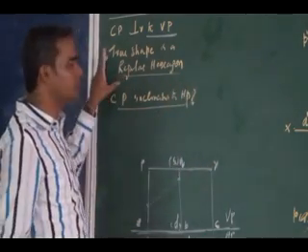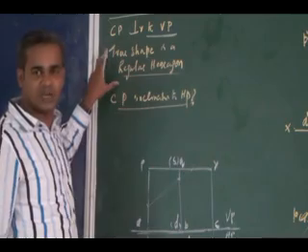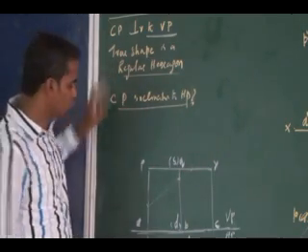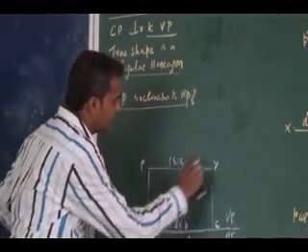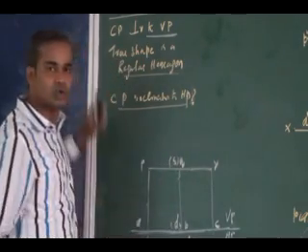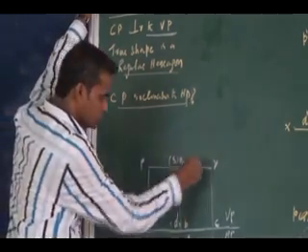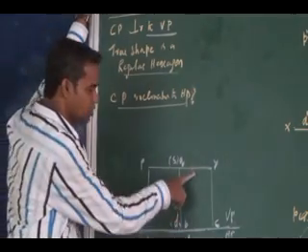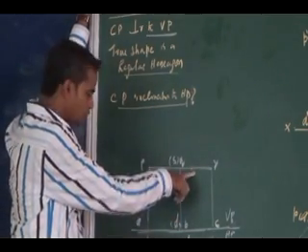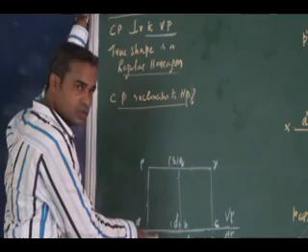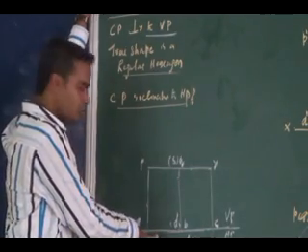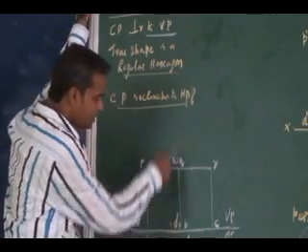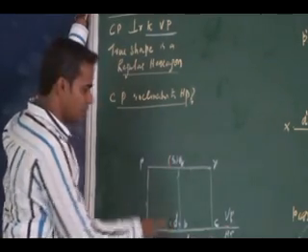So our true shape should hold 6 cutting points since it is a regular hexagon. So in which orientation can I cut this cube? If you see, this is the orientation where I should get 6 cutting points. It should cut the top base, I will get 2 cutting points. Then it should cut the bottom base, I will have 2 more cutting points, 4. Then it should cut the vertical edges which are in the middle in the front view.